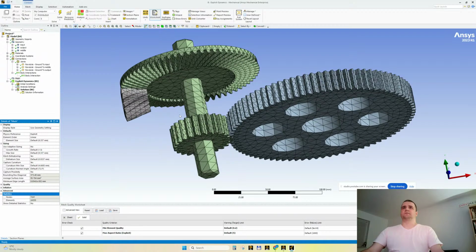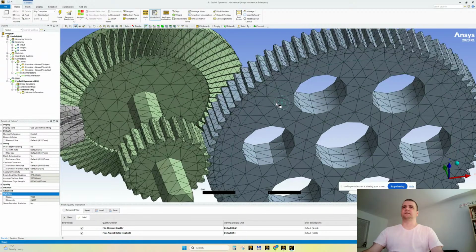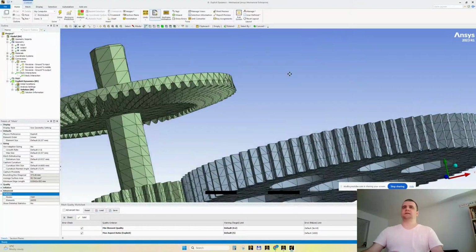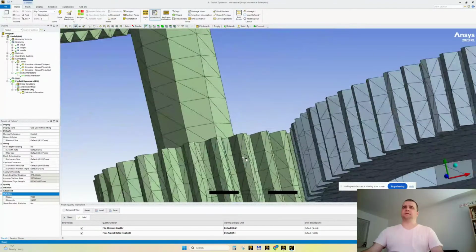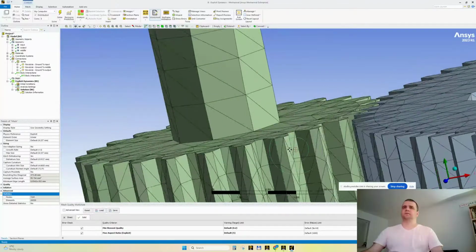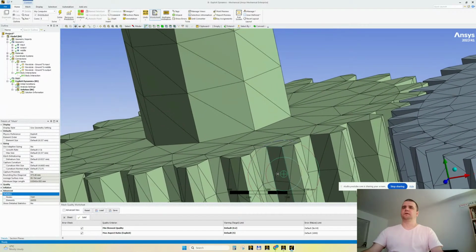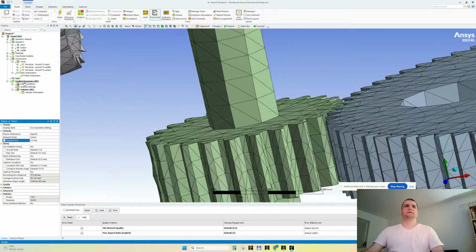It's kind of rough. It's very good for easier solving, but it's kind of rough. Let's get an idea about a thickness of a tooth, around 0.5. So between 0 and 5, so maybe around 3.5. Let's leave it like this and generate mesh.